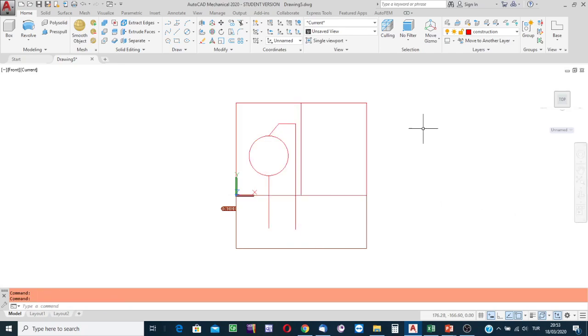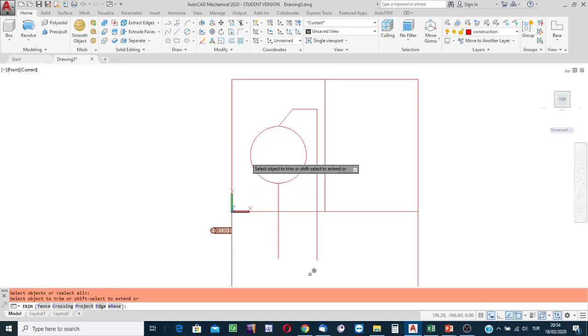I'm going to trim the further extended parts to be able to locate the terminal point of this boundary and the other boundary precisely along the boundary of the work plane. Start the trimming process by clicking on the trim button. And you know, in AutoCAD the trick, after starting the trimming process, don't forget to press enter and then indicate this further extension, the other further extension.